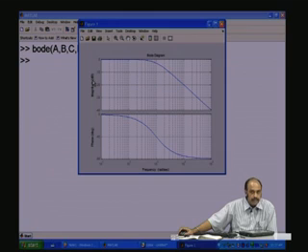So, 20 log base 10 the gain is the dB which is being plotted here. So, when you say it is 20 dB, you talk of 10 times amplification. Minus 20 dB means at this frequency there is a 1 by 10 attenuation. Minus 40 dB means at this point there will be a 100 times attenuation. So, if it is plus, it is amplification; if it is minus, it is attenuation.